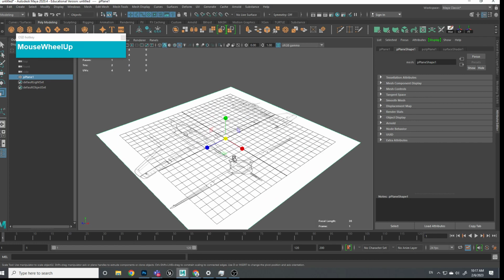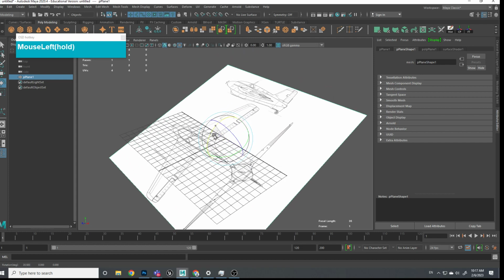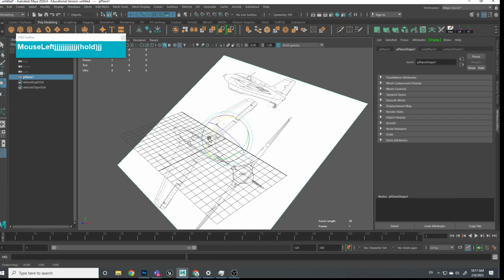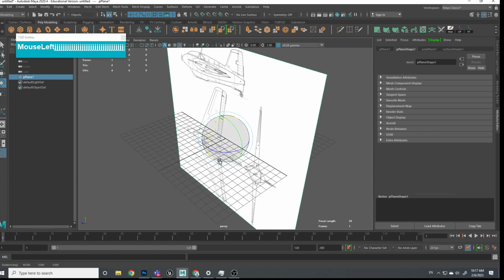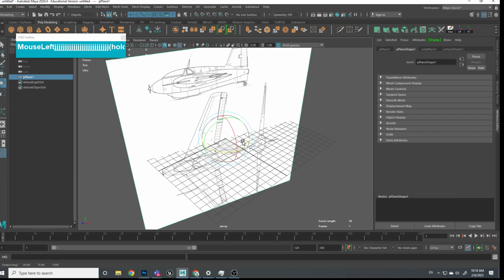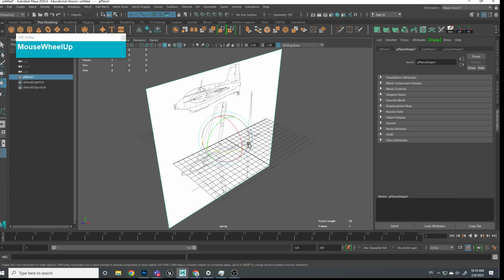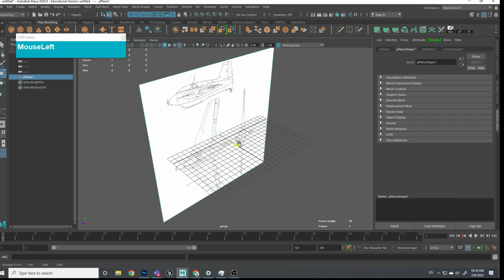So first you have to rotate the first plane. I want to line up my side view first. Remember the space shuttle now? Everything got a side view, front view, and top view. You have to line it according to the views. Y'all remember that? Okay, so let me undo this. Holding down the J and then rotating 90 degrees. I want to rotate this 90 degrees, holding down the J and grabbing the rotate tool. Remember your rotate tool is E. And then I'm going to press W to push this back.